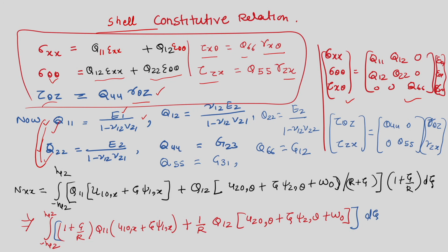Since I said that the present formulation is valid for a cross ply cylindrical shell, definitely one can develop a solution for an angle ply cylindrical shell, but here it is more generalized. So, Q16 and Q26 will also come into the picture, and we have to present symmetric and antisymmetric cases where the analytical solutions are valid. But for a general angle ply cylindrical shell, the analytical solution is not valid. Then we have to think of an approximate or finite element solution.